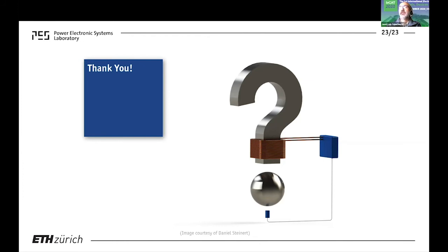Mm-hmm. And does it depend on the transducers you use? I mean, these were commercial transducers with a given size and power. So, did you try any different elements for manipulating different objects? Yes. So if you want to move to bigger objects, you have to go down with the frequency. Of course, you're limited somewhere there so that you remain in the non-audible or ultrasonic range. But we've also explored, for example, 25 kilohertz transducers, and then you can suspend bigger objects. Okay. Thank you.